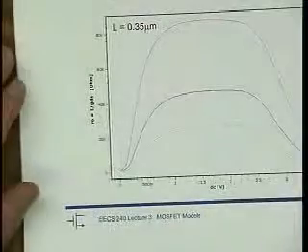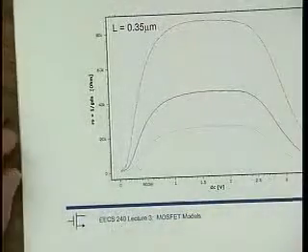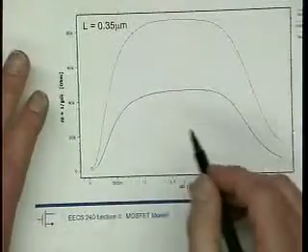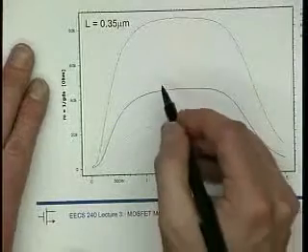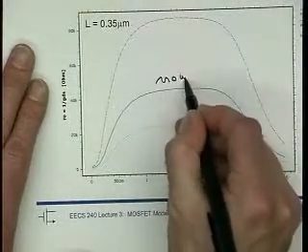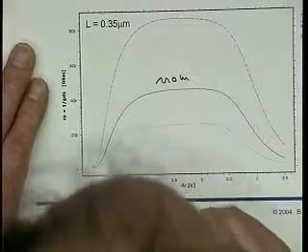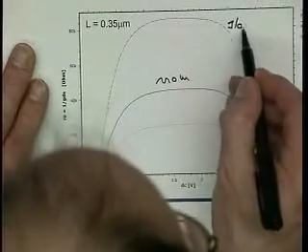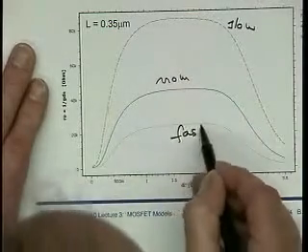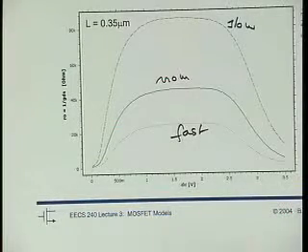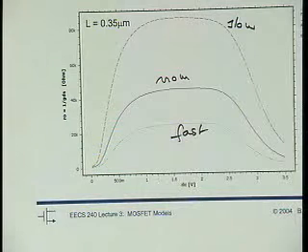Another issue with R-out is that it actually varies all over the place. Here I've made a nominal, fast... No, this is slow, and this is fast. I just ran those simulations with the different types of devices, and I found that the R-out varies by more than a factor of 2 in both ways.